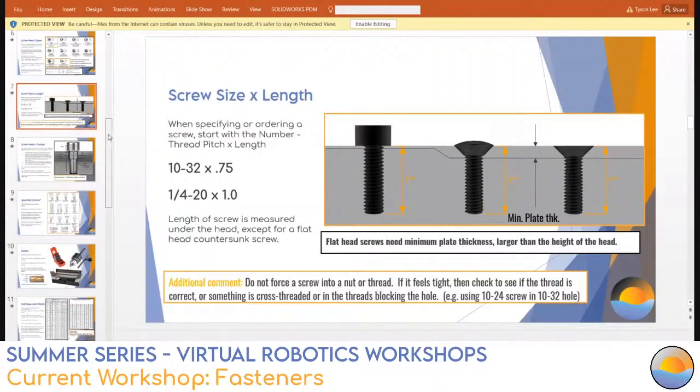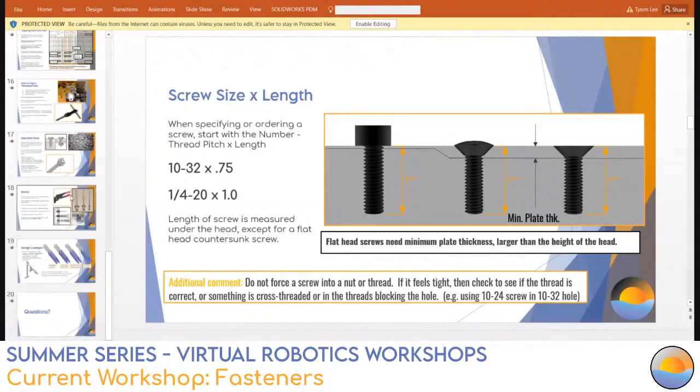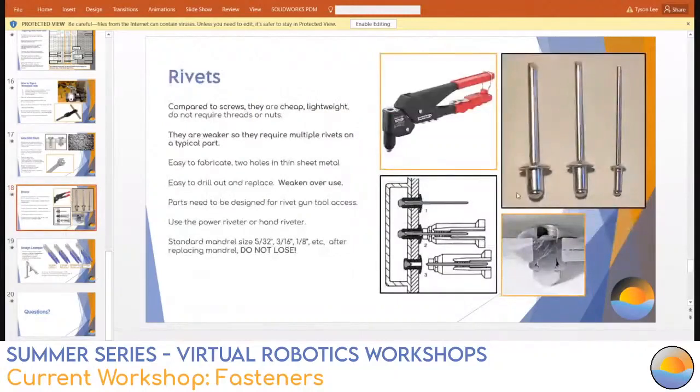But I forgot to mention that the drawback of regular rivets is that you can't easily take parts on and off without drilling them out and enlarging the hole. So you don't want to use rivets where you're going to take parts on and off frequently or potentially. Rivet nuts allow you to do that, and yes, I'd recommend it. I didn't want to get too far into it, since it's too much to explain considering the breadth of the information. I'm glad we were able to touch on that.